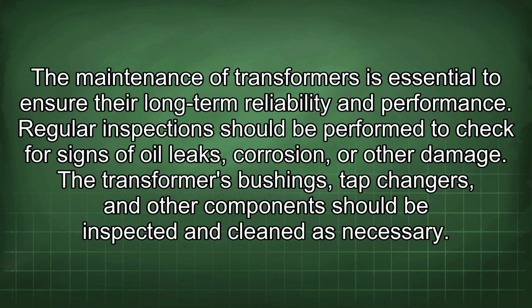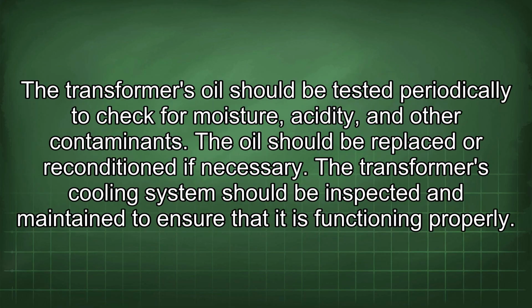The maintenance of transformers is essential to ensure their long-term reliability and performance. Regular inspections should be performed to check for signs of oil leaks, corrosion, or other damage. The transformer's bushings, tap changers, and other components should be inspected and cleaned as necessary. The transformer's oil should be tested periodically to check for moisture, acidity, and other contaminants. The oil should be replaced or reconditioned if necessary.